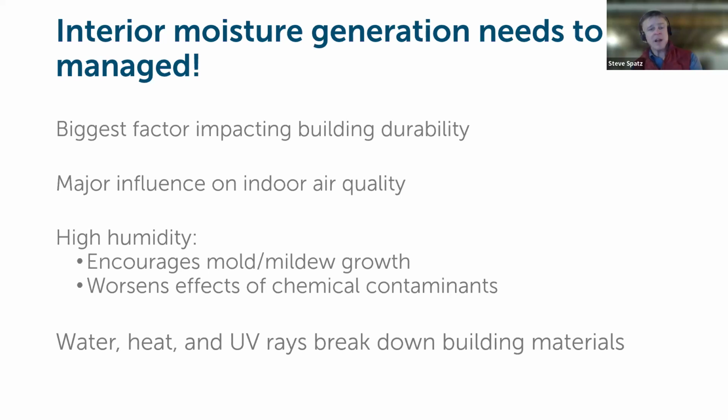A big factor when we talk about new construction is that there's a huge amount of moisture within a building for the first couple of heating seasons. Think about a foundation that's poured and you build a house right on top of it, and we build into the winter, and you're capturing so much embodied water in those assemblies just as part of normal construction practice. That loading needs to be accounted for, especially in those first few years, to bring it down to a manageable baseline, and then to manage the long-term indoor humidity for the occupants and for the assemblies.